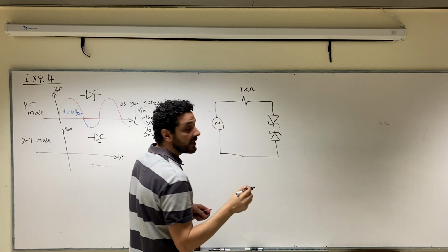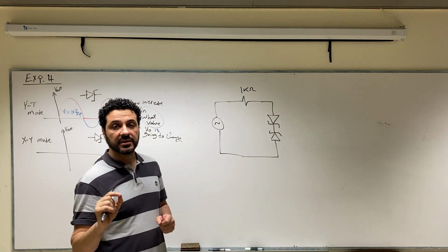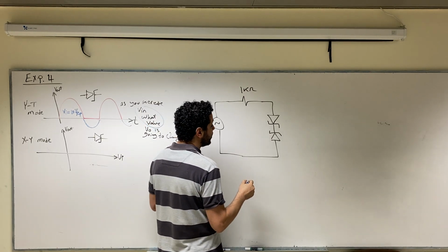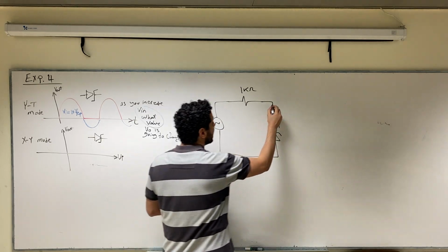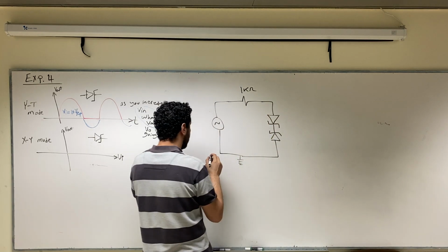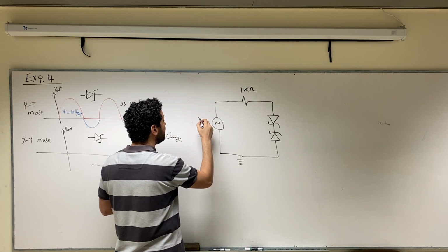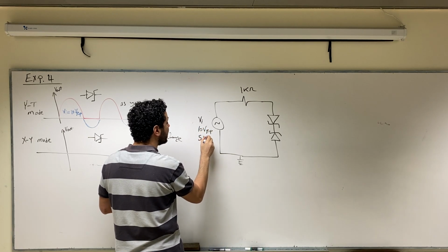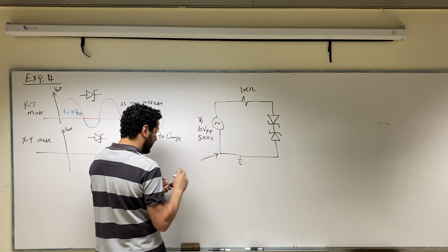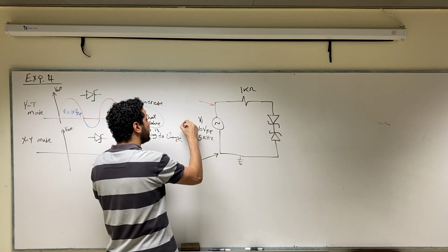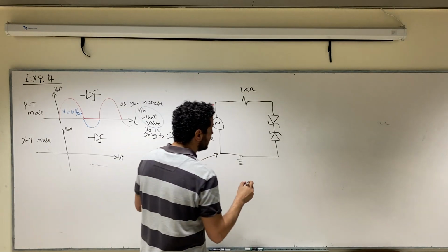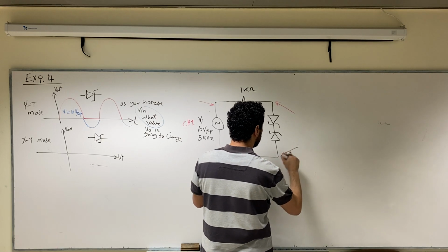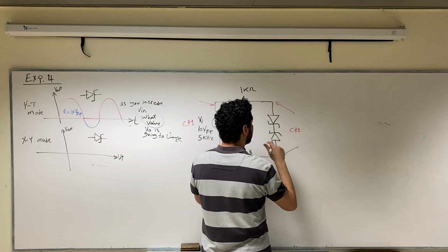So, 2 Zener diodes, and as we said, we are going to use here the small Zener diode with a breakdown that ranges between 2.1 and 3.6. The output here will be measured across this; this is our ground, and this is our source. Again, we'll use V input 10 volt peak to peak and 5 kilohertz frequency. By default, channel 1 of the oscilloscope is connected to the function generator, and we are going to connect channel 2 of the oscilloscope between these 2 terminals, and this will represent our output.